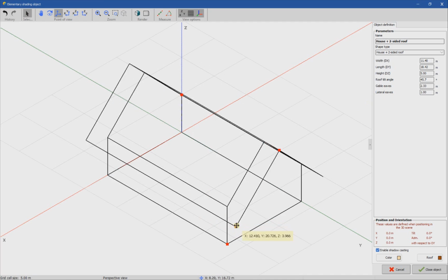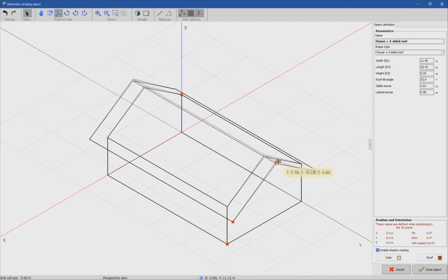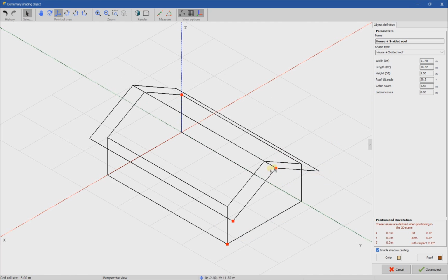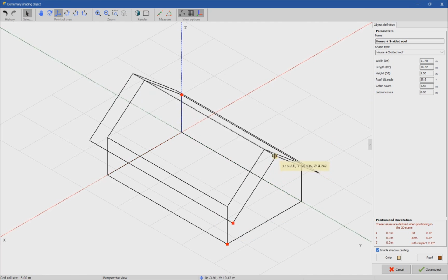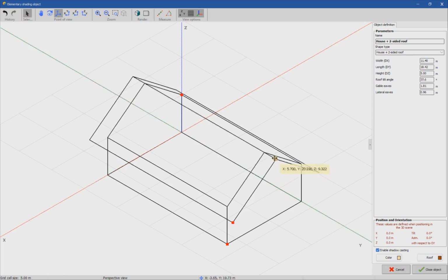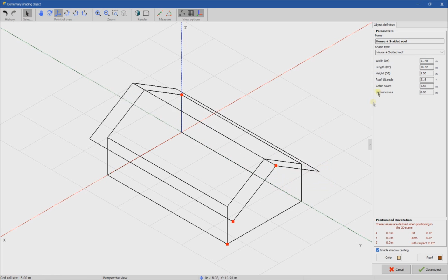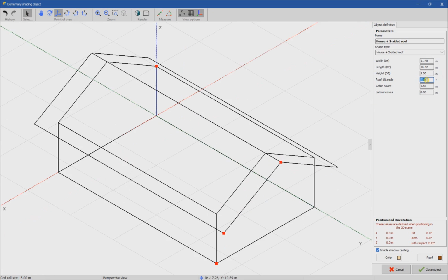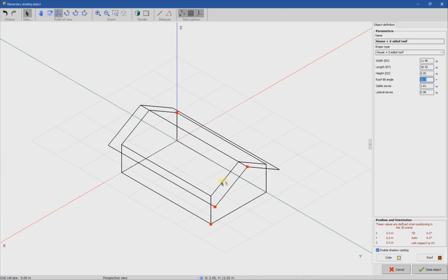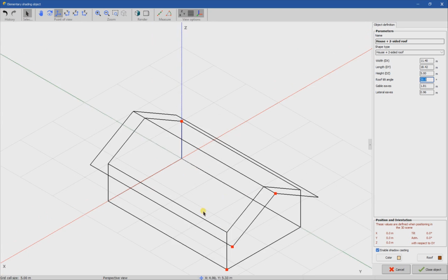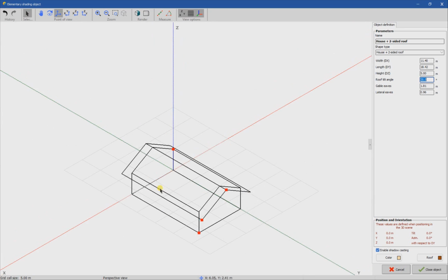Okay, like this. So you have many options you can do. Also, as you can see, by controlling this part here, you will see I can change the tilt angle. So if I have a roof of 30 degrees, I will simply say 30 degrees and enter. So this roof is now inclined by 30 degrees from the horizontal. All of this depends on what you see in the location itself.